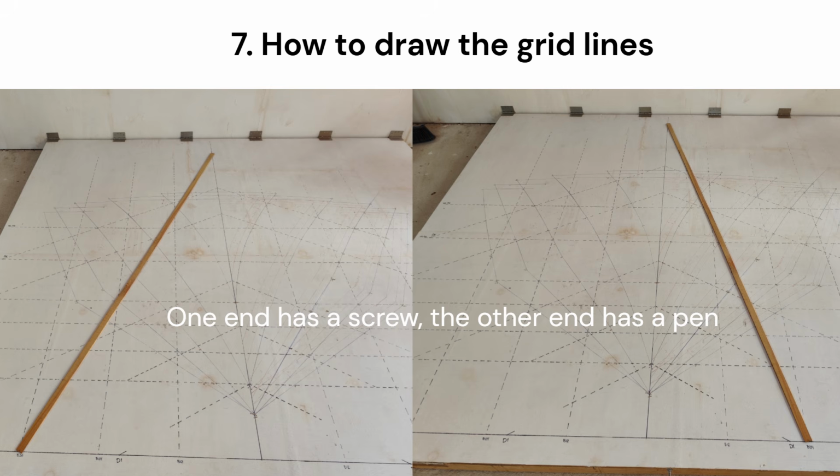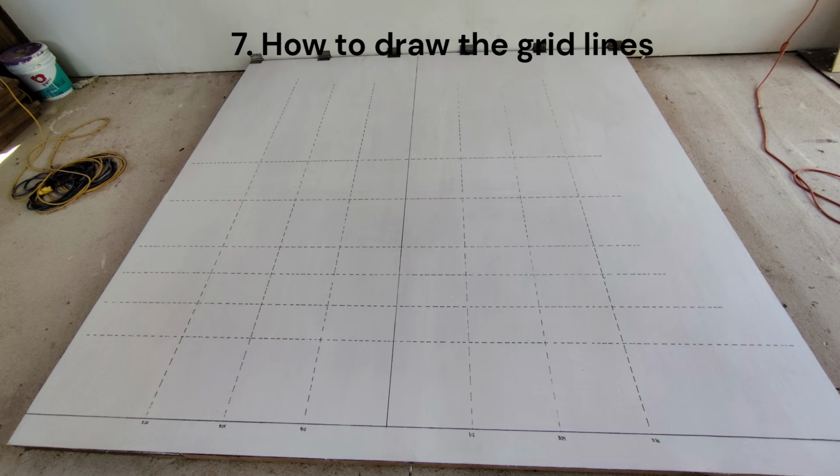Here we have used a 24-inch buttock point. Where these arcs cross, you have the mark for the vertical line. Use a straight ruler or similar to draw the straight line. Next come the water lines. Most people swing arcs for these as well, but you can also mark points to the left and right on the line close to the edge of the lofting table.